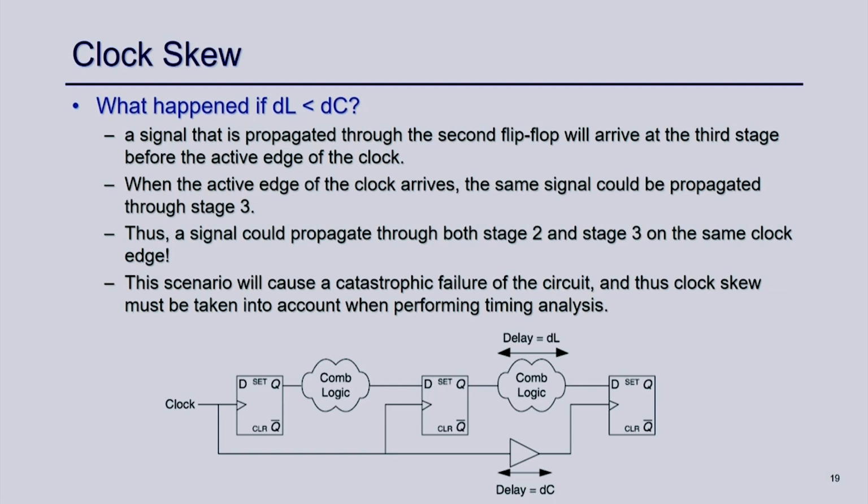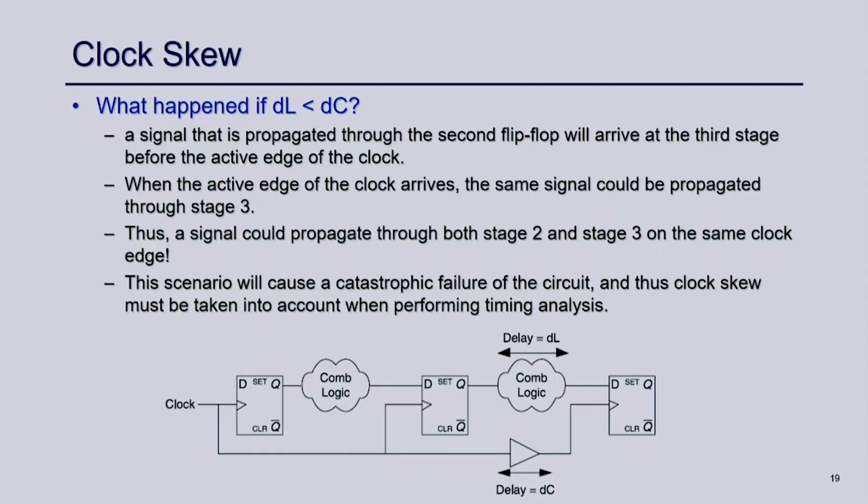So, when you are talking about clock, clock is something that is driving your digital circuit, right. It is actually driving all the registers, and most registers or flip flops are edge triggered. Whenever there is a positive edge, your circuit will toggle, right, your circuit's state will change, right. Now, we will talk about what is clock skew, right, and what the issues are, because primarily we are going to talk about the issues with clock. You should be careful. But the first thing we are going to talk about is clock skew.